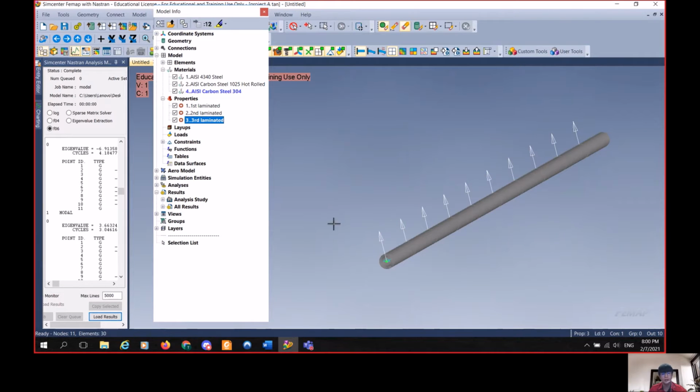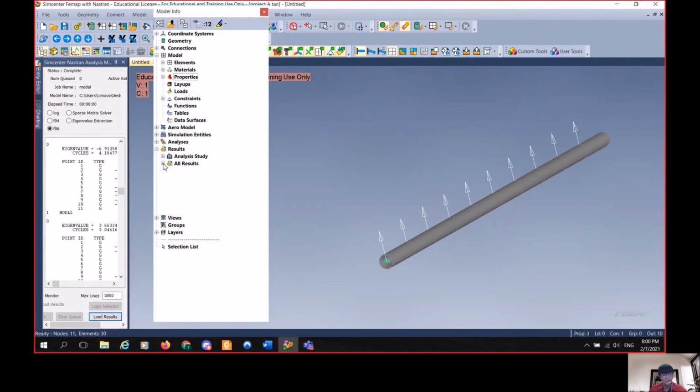After we have done building this and confirmed all the materials that we use, we proceed to constraint. For constraint, I have pinned both ends of this steel pipe, which are node 1 and node 11. After the constraint is done and all the boundary conditions are fixed, we can proceed to the next step, which is to analyze the new design pipe. After it has been analyzed, we can get this result. As we can see, there is a total of 10 modes, which represent the 10 elements in this new pipe. Each mode has its own natural frequency, and I will simulate it one by one.